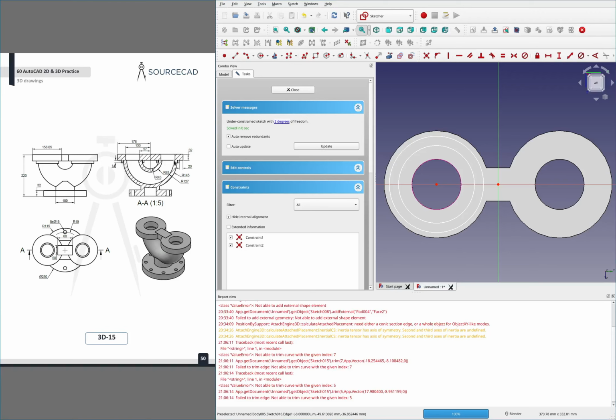You could do it in one shot here because we're not actually removing anything. If I had extruded this up before, like I was talking about, I would do this in two separate passes. I would do one loft and then one cut loft through the center of it. Since we're not doing that, this should be fine.